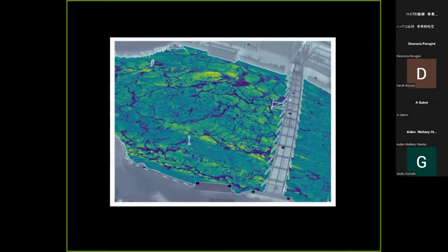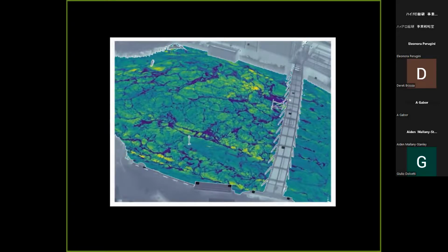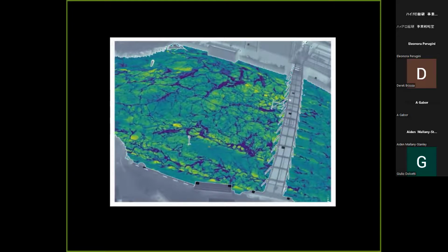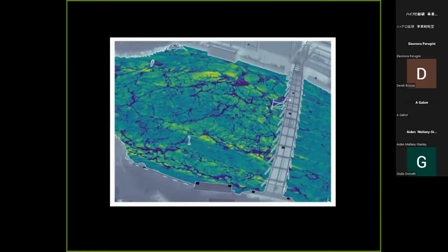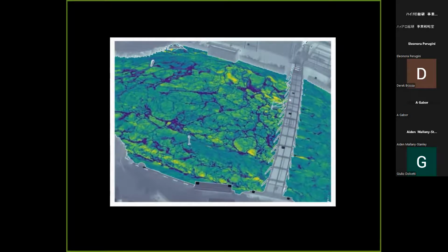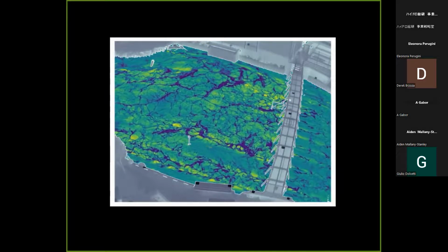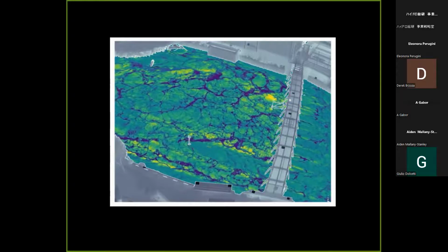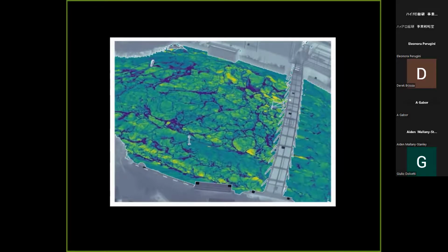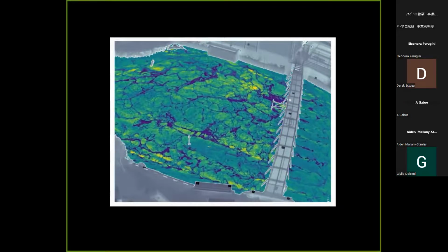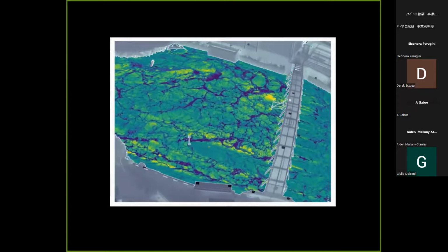Seth, just a bit added on to that: do you get any sort of seasonal effects, like with different levels of humidity over the water surface? Yeah, that's a really good point. The quality of the image, for the purposes of velocimetry, mostly has to do with how much heterogeneity there is at the surface. So how much texture do we see there that we can track. The greater the difference between air and water temperature, the better a signal we'll have, and humidity definitely plays a big part of that. So the metric we look at is the difference between water temperature and wet bulb air temperature, which incorporates humidity. And of course, we haven't measured in Michigan in the winter, but aside from ice, one can expect that the air-water temperature difference might not be particularly large, so that might present some other challenges.